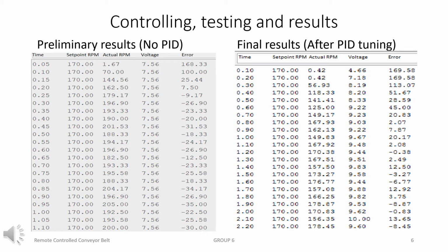The Bluetooth functionality was tested by pairing the Bluetooth modules present in the master and slave devices, entering changes in the master device, and viewing if those changes were affected in the slave device. After adjustments were made and changes made in the master device were able to be sent and then received by the slave device, the Bluetooth functionality was deemed successful.